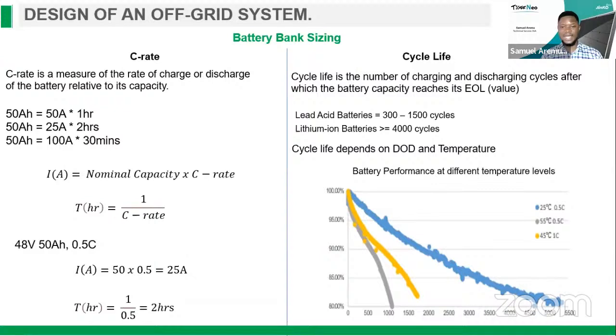That means your battery will last 365 cycles over the number of cycles you do in a year. So in a year you have 365 cycles, which means your battery can only last one year before it reaches end of life. But if you discharge only one cycle every other day, your battery would last longer than a year.